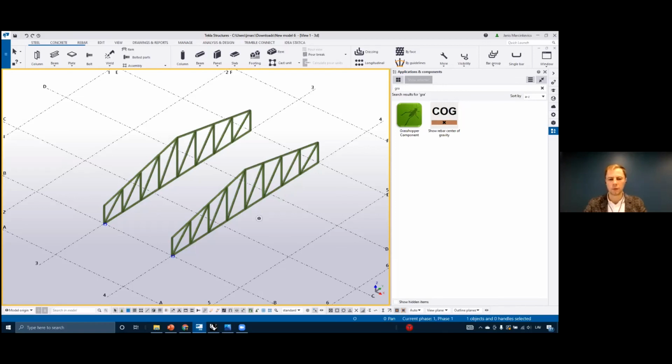Then the question is: can I use this approach to calculate reinforced concrete structures? I guess it was because you showed steel structures. Yeah. If you're talking about Karamba, there are some limitations, but for shell structures you can calculate the reinforcement. If you're talking about beams and columns, then you can of course get the forces, but the reinforcement design itself you should do, for example, in Excel. But it's so easy to transfer the data. If you already have your spreadsheet that calculates the reinforcement, or if you are using Tekla TEDS, which also has a link with Grasshopper, you can send the data from Grasshopper to Tekla TEDS, do the reinforcement design there, and get back the results. So it's possible. Yeah, thanks.